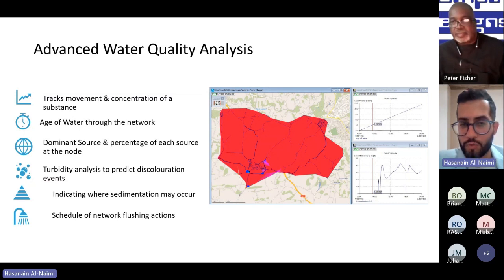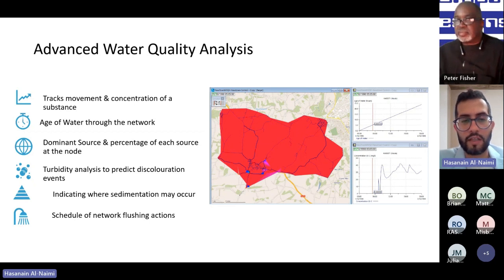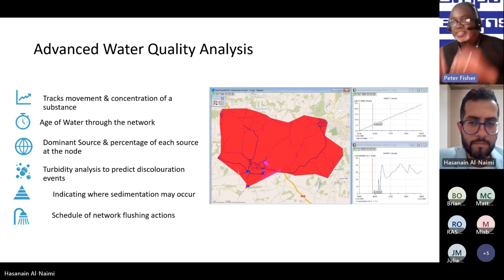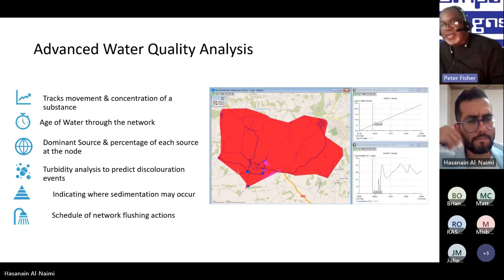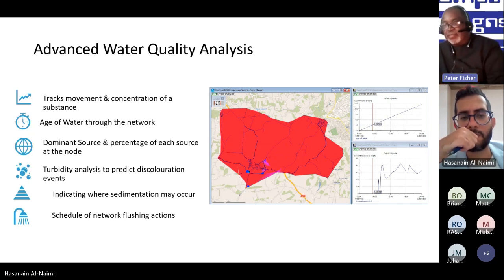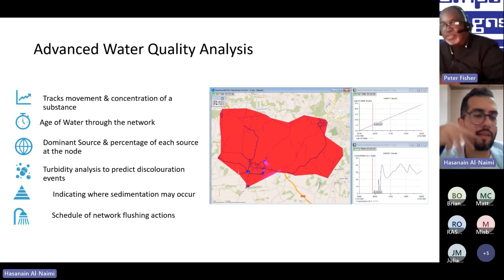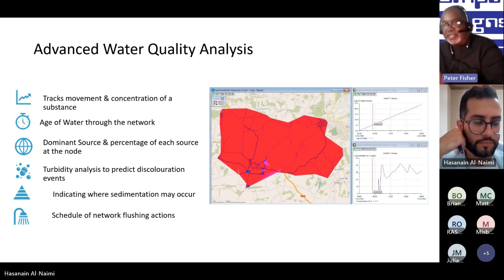But here we're speaking about the age of water. So if that's your question, you have the ability to change it. I think his question was about as a pipe ages, the losses due to friction and the roughness of the pipe also increase, and the pressure required to drive water through that pipe also increases. How do you factor that into the model?